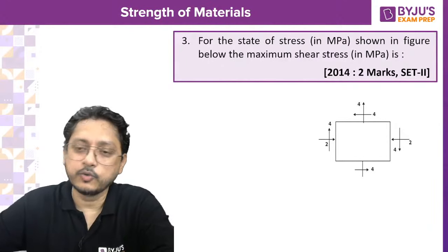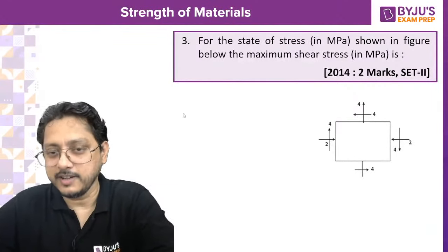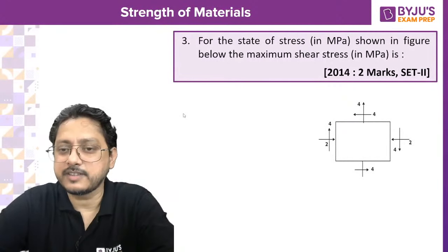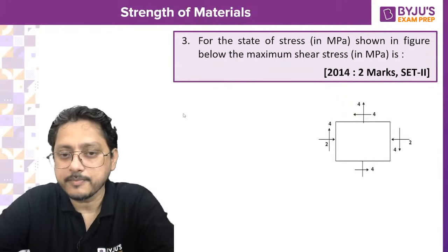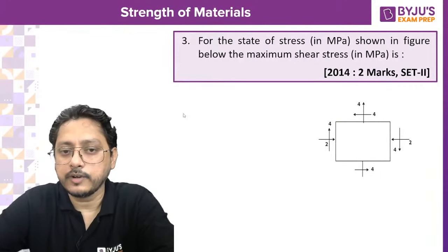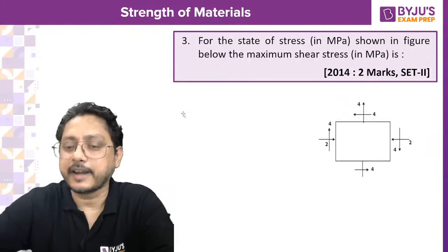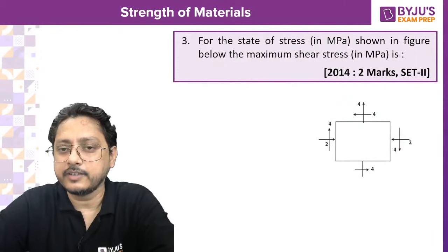See, at least for 2D, you know that this is the maximum condition one can imagine, isn't it? There is nothing more than that one can ask. So maximum shear stress, either you can calculate through the Mohr circle, or you can directly utilize your formula. In the Mohr circle, what is that maximum shear stress? It is nothing but the radius of the Mohr circle.